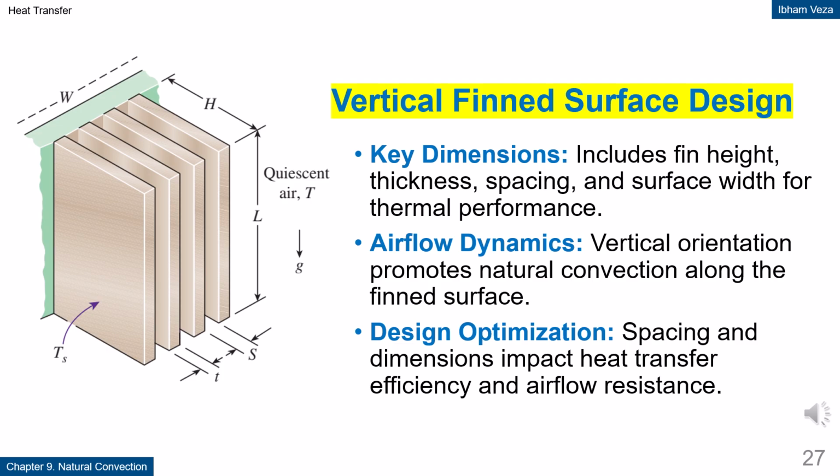Vertical finned surface design. The thermal performance of a finned surface is determined by fin height, thickness, and spacing. Vertical orientation helps strengthen natural convection flow. Air rises through the gaps between fins and carries heat upward. If the spacing is too narrow, the flow can be restricted. Therefore, geometric dimensions must be carefully designed.